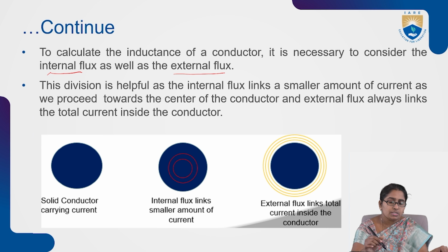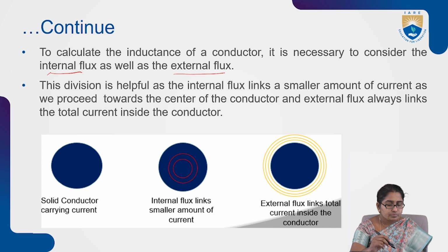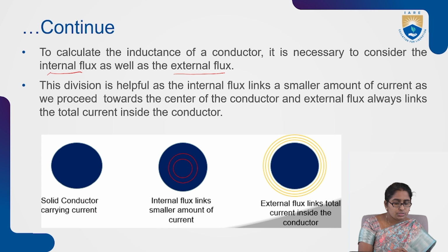Now, this division is helpful as the internal flux links a smaller amount of current as we proceed towards the center of the conductor, and the external flux always links the total current inside the conductor. Okay, so this is what it shows.